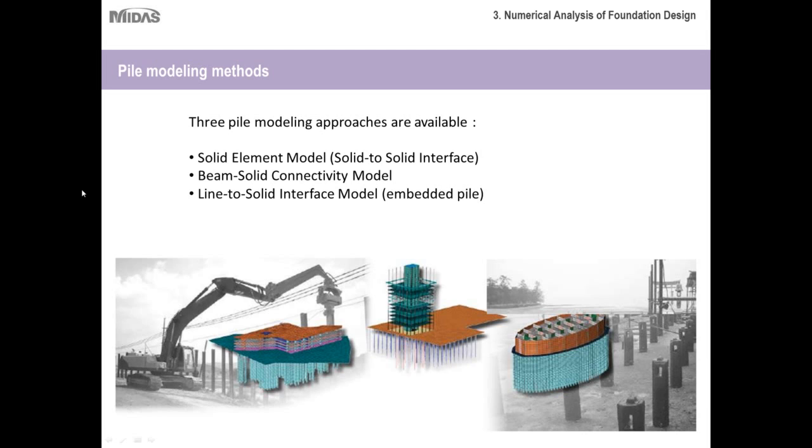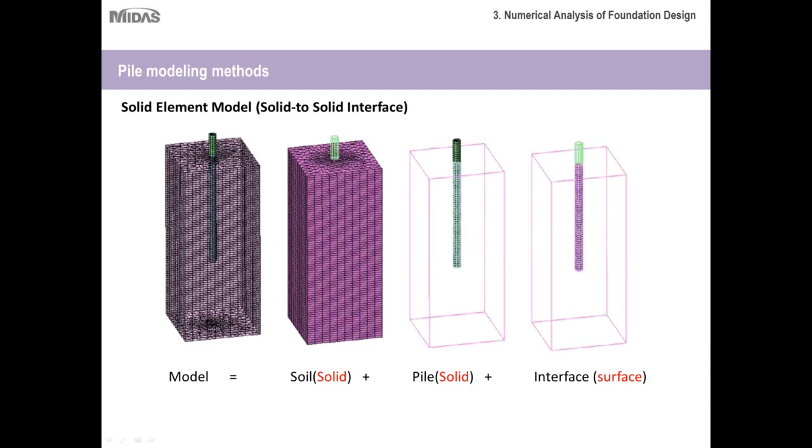So we have three pile modeling methods here. First is solid element modeling, second is beam solid connectivity, and third is line to solid interface model, which is also called embedded pile model. So let's take up each one of these modeling approaches individually.